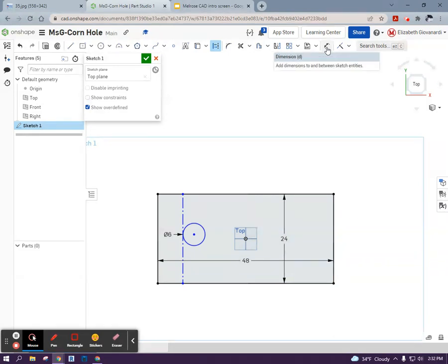But first, I'm going to say that that line is 9 inches down from the top. So I'm going to click the line and click the top edge of the board. And you don't want this to happen. You want it to just stay in there. And I'm going to say 9. That's great, but now you can see my circle still has nothing to do with that line because we haven't constrained it yet. So you can move this around, see that you can move it.